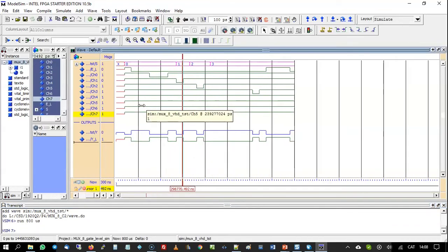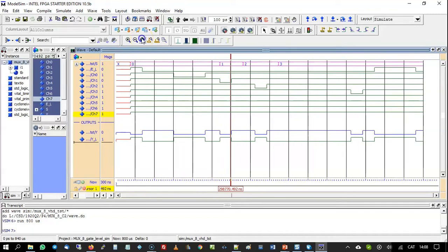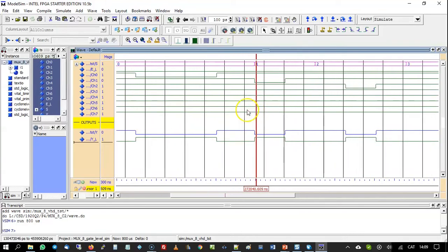You see? This means that at least it works up to this level, and I mean the level of zoom full, right? If you zoom full, you see the waveforms the same way as you saw them when you did it by means of the functional simulation. So right, now you put the time cursor in some transition when you see that the output is going to change. For example, here, that's the transition. And now this time you will go zooming this.